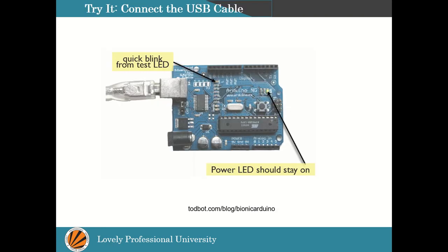Let's start. So first of all, it will look like this. It will have a cable, and once you plug it into the USB port of the laptop, this power LED should stay on. And this is the LED that is on board, that is by default connected with pin number 13. The first program that we are going to write now is to blink this LED.